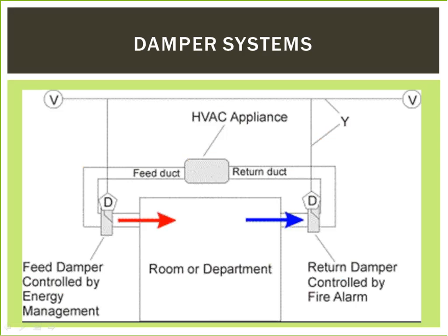Automatic dampers are used to regulate airflow constantly and are operated by electric or pneumatic motors, in turn controlled by a thermostat or building automation system. Automatic or motorized dampers may also be controlled by a solenoid and the degree of airflow calibrated, perhaps according to signals from the thermostat going to the actuator of the damper in order to modulate the flow of air-conditioned air in order to effect climate control.